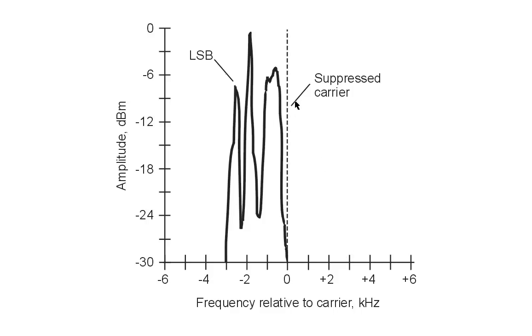But the important thing here is that in a single sideband signal, the carrier itself, which existed in the original amplitude modulated signal, is suppressed, and that is done typically by a circuit called a balanced modulator. A balanced modulator takes an AM input and provides a double sideband suppressed carrier output, and then we can get rid of one sideband or the other using a highly selective filter.